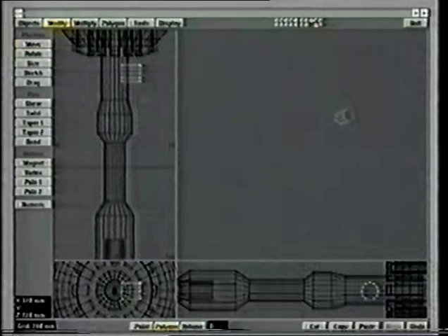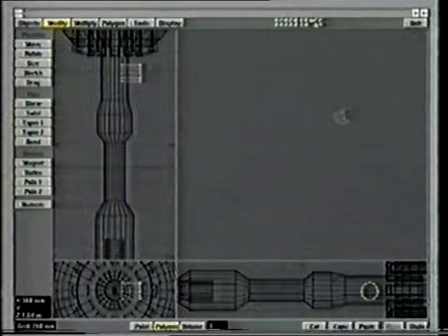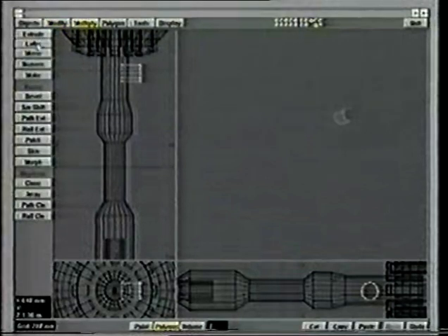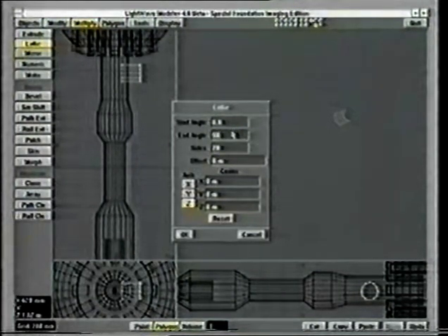Okay, now I'm going to select the end polygon. As I'm going to continue extruding this, every time I do it, I need to flip the polygon. Otherwise, the pipe will basically alternate between having inside-out polygons and outside-out polygons. So I'll hit the F key to flip it, and then what I want to do is multiply lathe, numeric. Now, here I only want to go 90 degrees. Whether it's plus 90 or minus 90, we will find out.